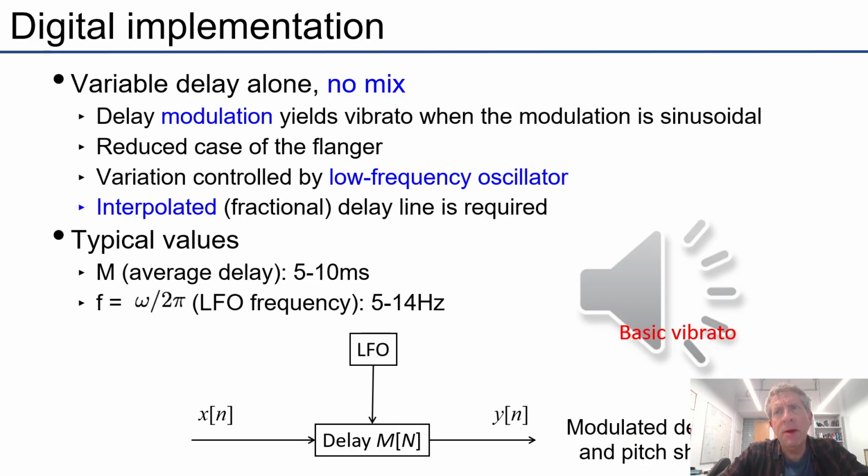So how is it implemented? It's just a delay line, but the trick is to vary the delay in the delay line. So when the modulation that is being applied is something like a sinusoid, then that's similar to the modulation of a finger wiggling on a violin, or the modulation that a singer might do with the vocal cords. So it's somewhat smooth in its behavior. It's not jumping like a square wave might from one value to the next.